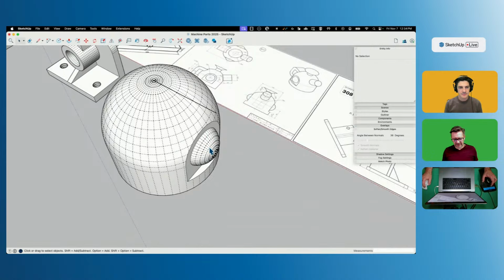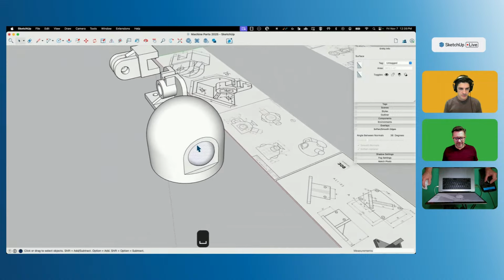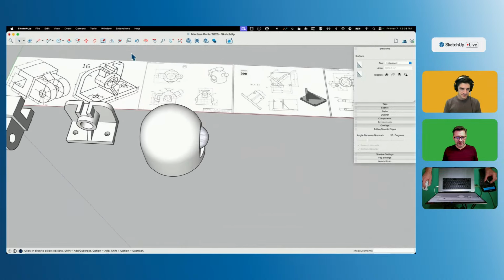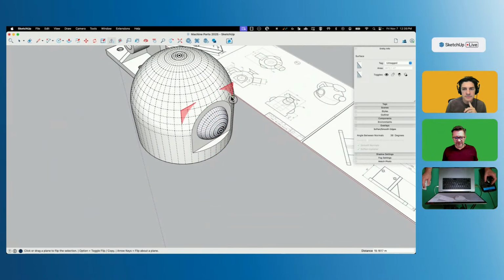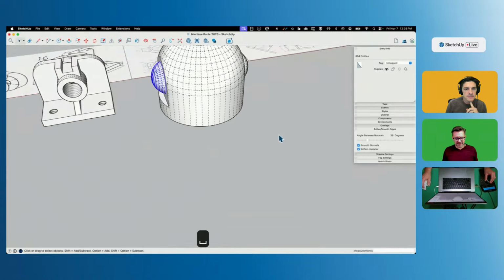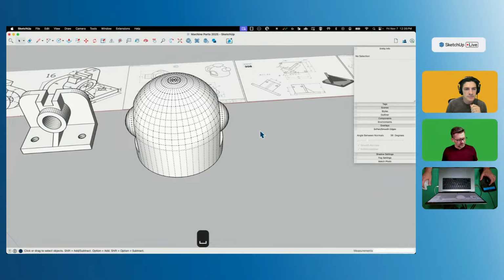So what I'm going to do is grab, oops, I hit undo instead of, I hit undo again. There we go. Grab that now. I want to put that on the other side. So we'll say mirror that. And I'm going to toggle the hidden back on again. I use hidden geometry a lot when I do domes and that kind of stuff. So we're coming back to this point, and that'll give me one on either side. Those are done.